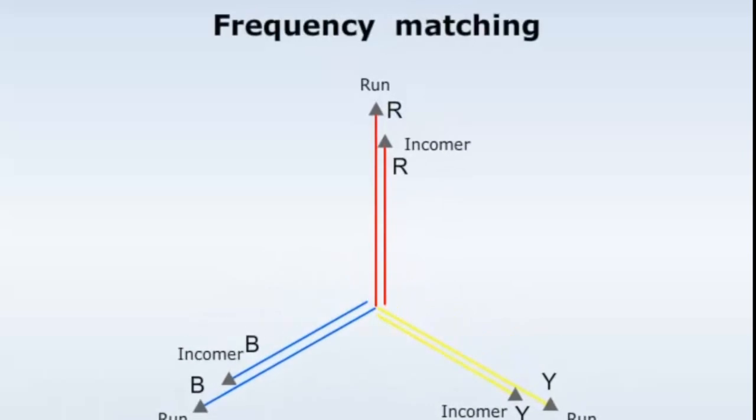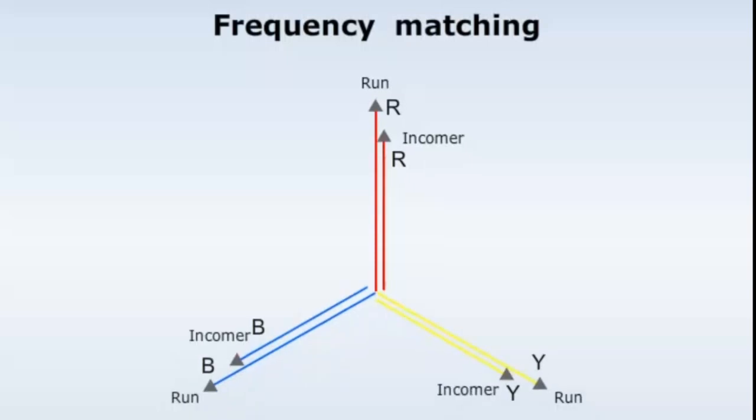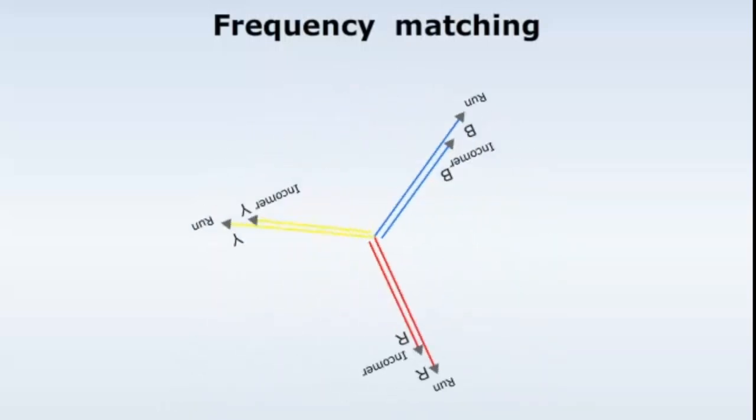The third condition is that the frequency of the incoming alternator should be matched with the frequency of the running alternator. The frequency of the incoming alternator and the running alternator will be equal when the alternators are rotating at the same speed.